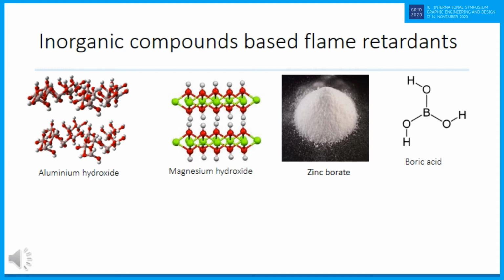When aluminum hydroxide is heated, an endothermic reaction occurs and it separates to form water and aluminum oxide. When the water is formed, it transfers to the vapor phase and causes the reduction of heat transfer during combustion. Mineral containing flame retardants are generally applied in thermosets for electric equipment, vehicles, and panels.